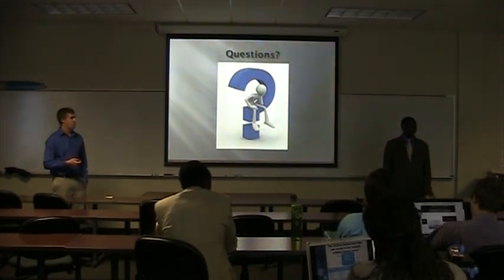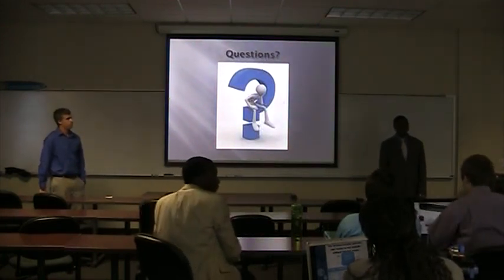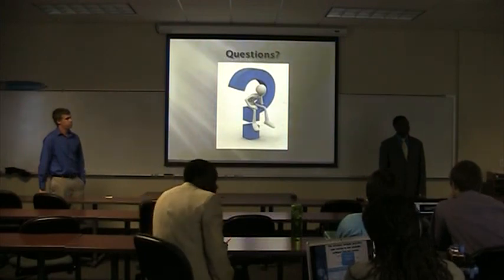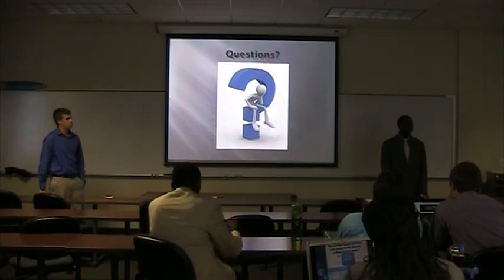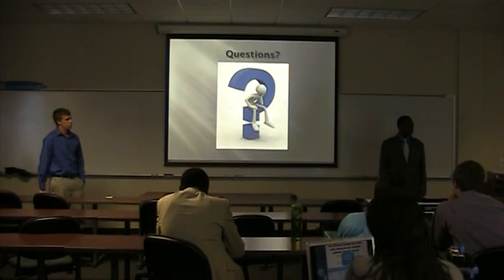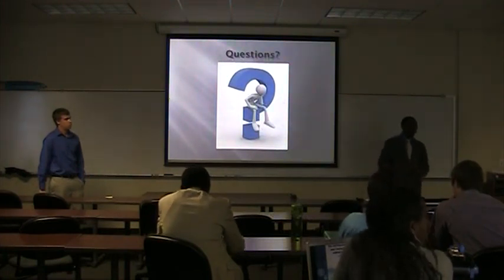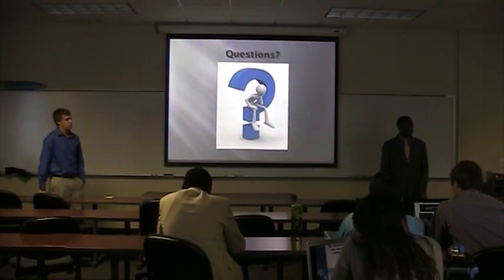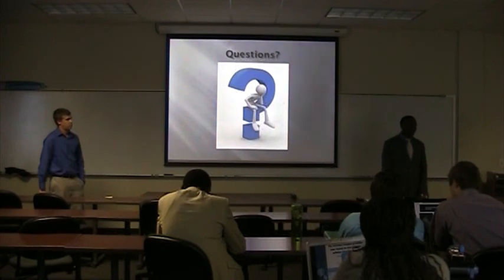Yeah. So we have the calculations we have done for how long it is going to take to use the solar panel. We found that the client wants to be able to use the laptop with it for about 8 hours. So on our calculations, with the battery full, we found out that it can be done up to 10 hours. So we're going to test it and see if it can match those calculations as well.